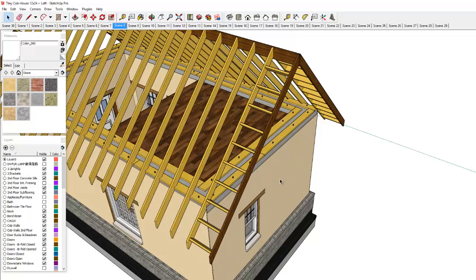Normally with a cob building, it is one monolithic piece. With a rammed earth building, you usually have panels. So this particular wall would be one panel. This whole wall might be one or two or three panels, and so on. So the bond beam would hold all the panels together. With the cob building, the bond beam still helps serve that purpose, just less so because the cob is held together with the natural fiber rebar.